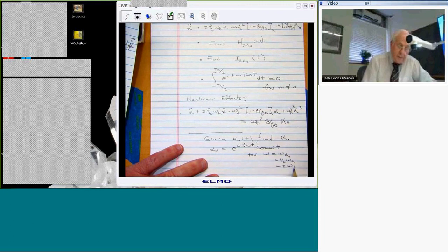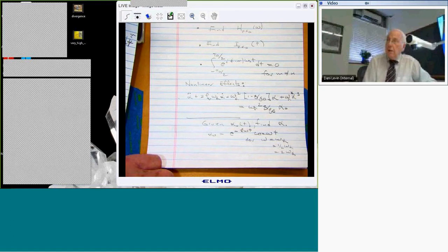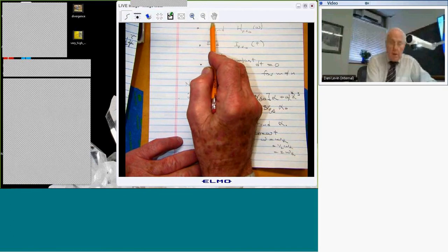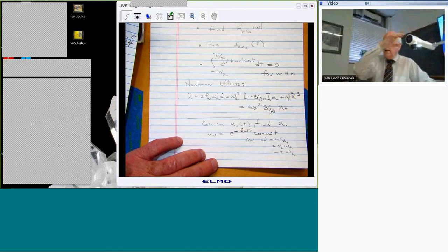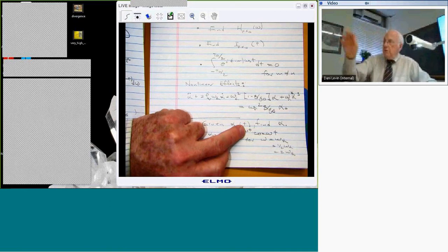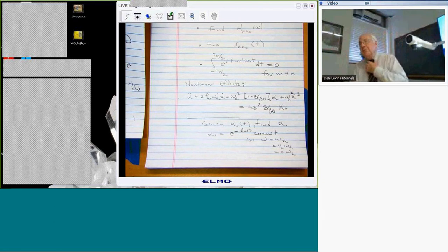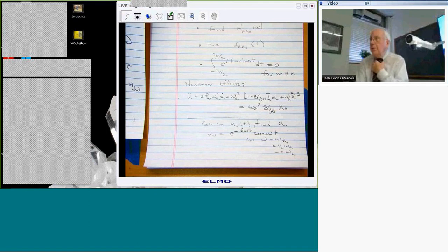Zeta is the same as the delta? Say again? Well, this is not the damping. This is the physical damping in the model, but this is just a decay constant that says how the input is decaying with time. If zeta equals 0, then this is just oscillating with a certain frequency forever, right? In which case, since it's periodic in time, you don't need the Fourier integral. You could just use the Fourier series. I want this to be a transient because otherwise it's periodic in time, and then you don't need all the apparatus of Fourier transforms and Fourier integrals.